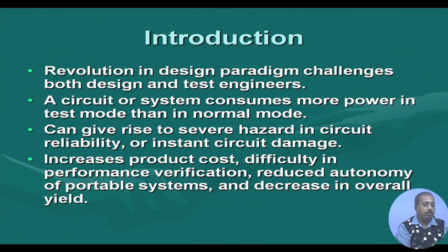Reliability may be a question because of this power consumption. A good amount of power is converted to heat, and that way it will increase the temperature, and if the temperature increases, then the delay of the circuit will also change. If all portions of the circuit are not uniformly heated, then the delays of different parts may be different.